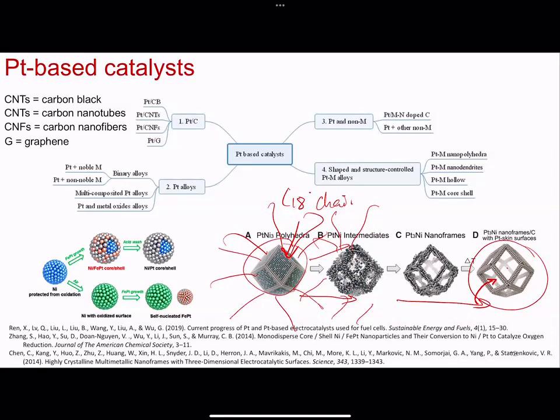And then once that's deposited, you can put that in the oven. You can acid etch it. You can dunk it in a little bit of acid, and all these hydrocarbon chains go away. But now you won't have agglomeration because the particles are deposited on a support that will keep them all apart. And that's what you see in a fuel cell electrode: whatever nanostructure material you have, they're deposited on a support that keeps the particles from agglomerating.